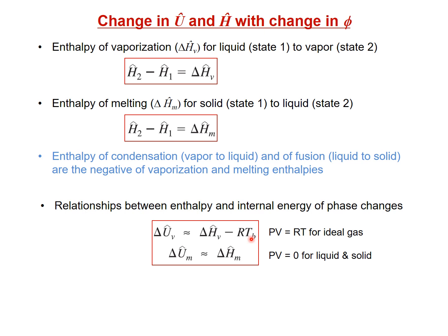This is about the vaporization. Then let's go to the melting situation, for liquid and solid. Of course, melting means the phase changes from solid to liquid. Then in that case, the enthalpy is the internal energy, because the PV term for liquid and solid is approximated by 0.